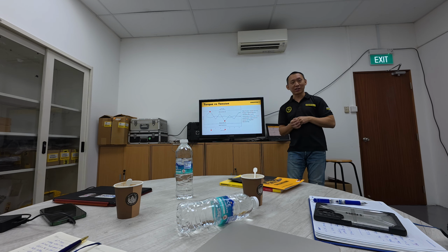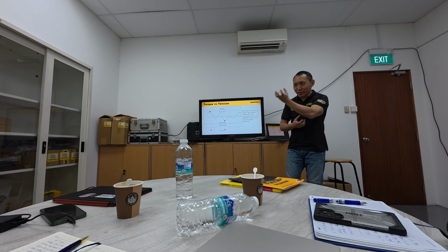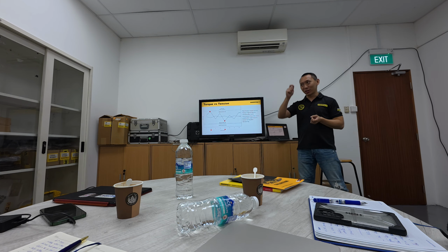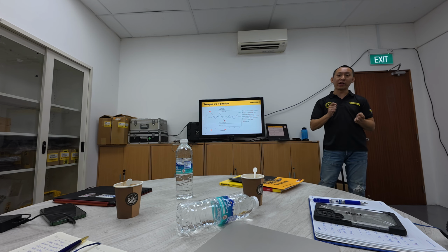Torque wrench may be faster, because if you use a tensioner, it is one tensioner to one point. It takes many days to get it right, and it is very complex because you have to do a lot of detailing to find out. So it really depends on the situation, the budget and the timeline.